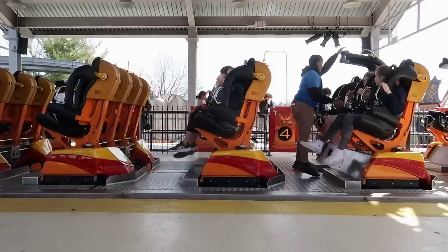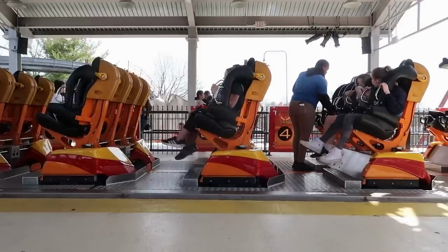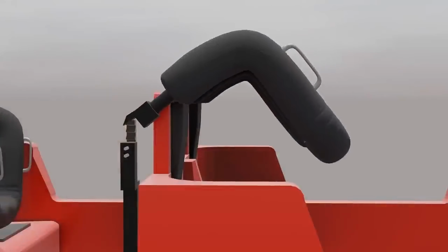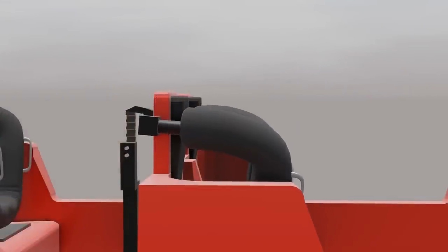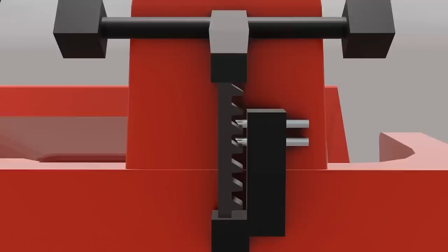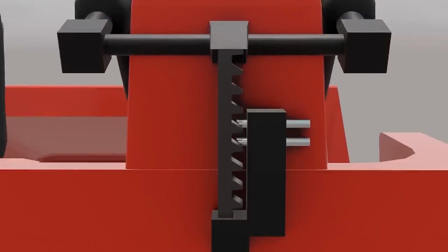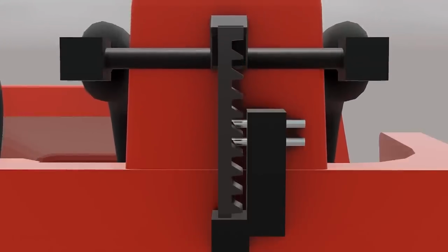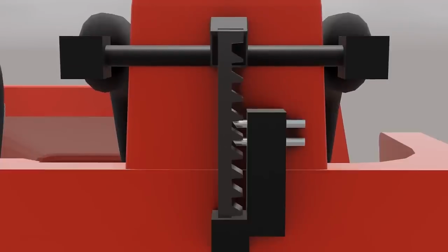On B&M rides, for example, they have 8 different settings. If a rider does not fit one of these settings perfectly, they will have some play in their restraint. This causes some riders to be concerned. However, this is how the restraints are designed. These types of restraints can also experience a problem known as a slipped ratchet.